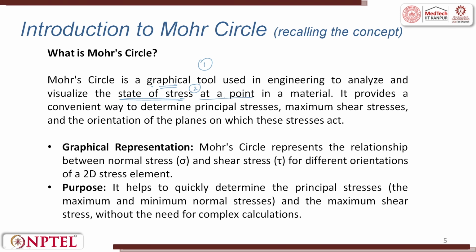This is important. So, graphical tool, state of stress at a given point in a material. It provides a convenient way to determine principal stresses, maximum shear stress and the orientation of the planes on which the stresses act. So, the important point is that it is a graphical tool.